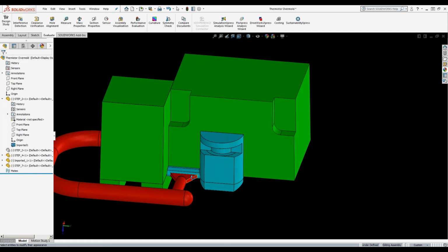Are these molds aluminum? Yes. We will insert out with steel where necessary if we have thin tool conditions, small features, anything like that. But main core cavities are QC10 aluminum, which is a high-grade aluminum. There are instances where we built the entire tool and all the inserting with aluminum, and due to wear issues or, as John said, ability to maintain a very small detailed feature, just a few thousandths thick, sometimes we will upgrade, per se, the inserts to a P20 or a steel material if necessary.